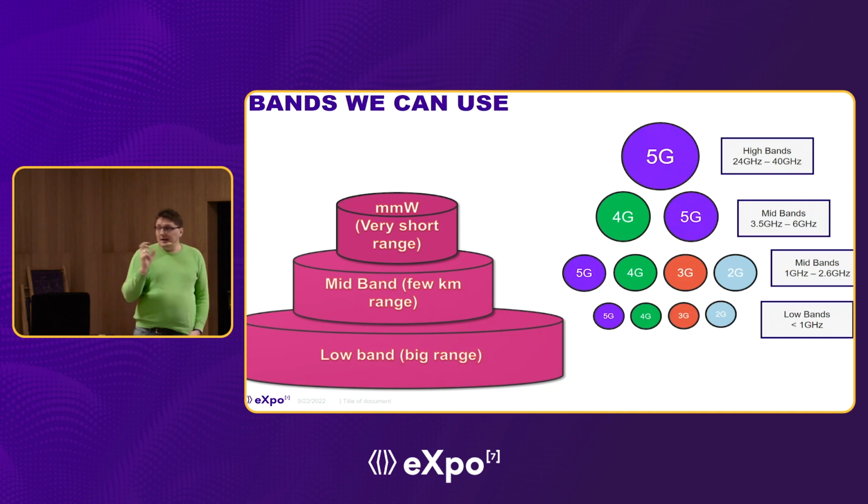we are cutting time in half. So we are giving the Doppler effect less time to damage our waves. And if you look at the range of the high bands, they have a very big range when it comes to frequencies, between 24 and 40 gigahertz. So we have like 16 gigahertz to operate on. For example, in the mid bands used at the beginning of 4G, we have only 1 to 6 gigahertz. So on the mid bands, increasing the spacing of the carrier, so increasing the usage of the bandwidth, was very costly because we have a very small bandwidth to operate with. On 5G, it's not so costly because we have such wide bandwidth that we can pay the cost and decrease the time. This is the first reason why we introduced new numerology.